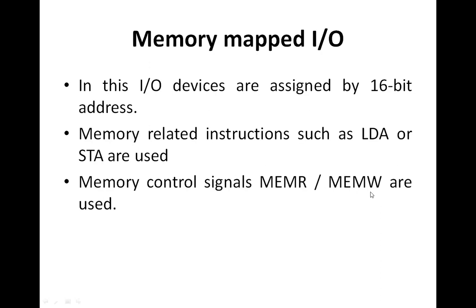So for all the operations used to interface the input output devices with the microprocessor, in the peripheral mapped input output mode, there is an 8-bit address, separate instructions IN and OUT, and separate control signals generated, input output read or input output write.